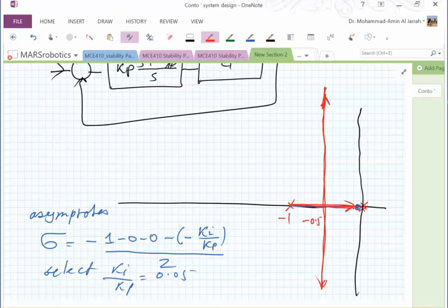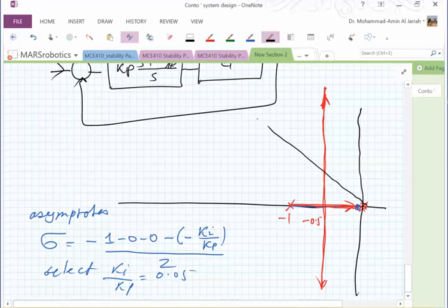So you know now why we want to get the 0 very close to the origin. Now let me show you why else we want to do this. We know from our performance criteria that we want zeta to be 0.707, right? So this is the desired location of the roots.